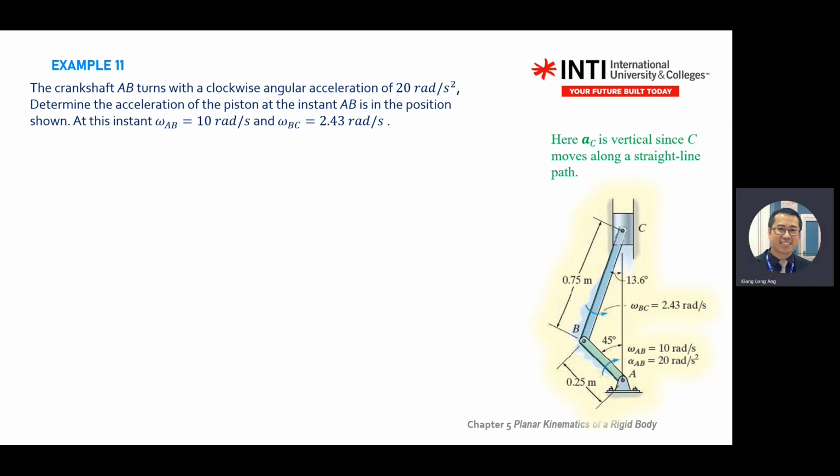Here you see a non-conventional triangle. You see this shape, quickly call your cosine rules. Draw a triangle, write cosine rules over there. Label ABC and all the angles as your reference, right? So you're given the angular velocity for link BC and AB. This one, you dissect, you do it slowly, one by one.